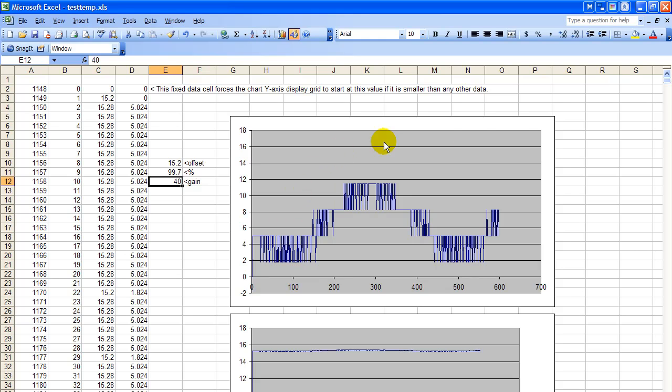So that's how you use this process. You need to go back over it. It's very effective. It allows you to look at trigger sampling in the middle of the buffer by stripping off the unnecessary stuff you don't want to look at. Get rid of the first 1147 data points. And we rescale the chart so it starts with sequence 0 instead of sequence 1148, and then we can do complex formulas on column D to show the results.